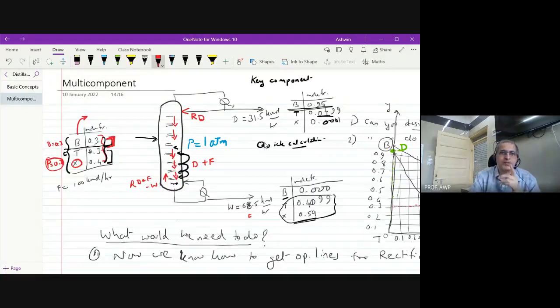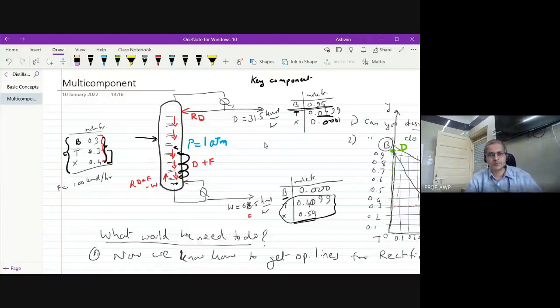But it is dangerous to do this. For this benzene, toluene, xylene system, we are simply using Raoult's law. Therefore, it is okay to do this. But it is not a good idea to do this because the third component can have a significant impact on the separation. What the third component is matters. Suppose it is benzene, toluene and water, or benzene, toluene and xylene, or benzene, toluene and ethanol. So what the component is does make a difference. So it is not a good idea in general to treat it as a pseudo binary mixture. But just to give you an idea of what we are separating in this column: we are separating essentially benzene from toluene. Do you agree with that?